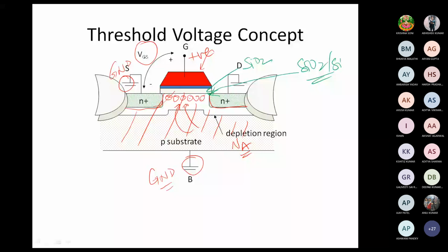As we put some charge by applying a positive gate voltage on the gate, equivalent charge starts building up on the other side because of the capacitive effect. We see a capacitive effect start working, because on both sides of the silicon dioxide we have conductive regions. On one side it is polysilicon, on the other side it is silicon, but that is doped, so that has some conductivity.